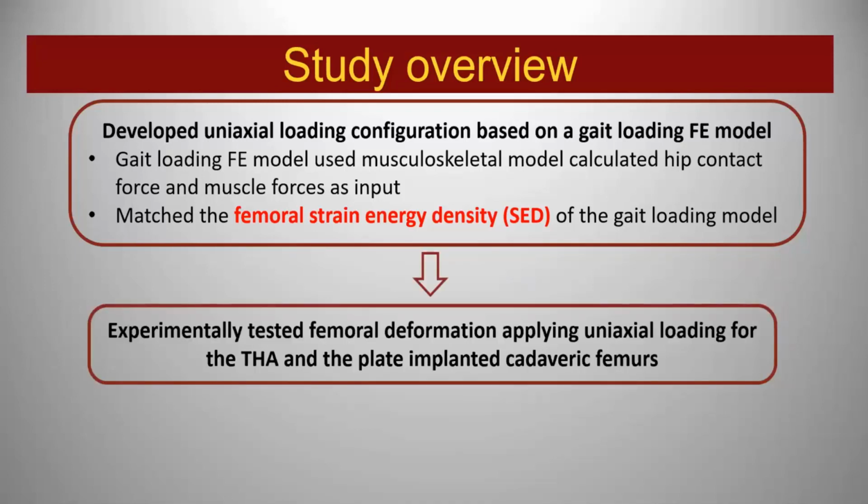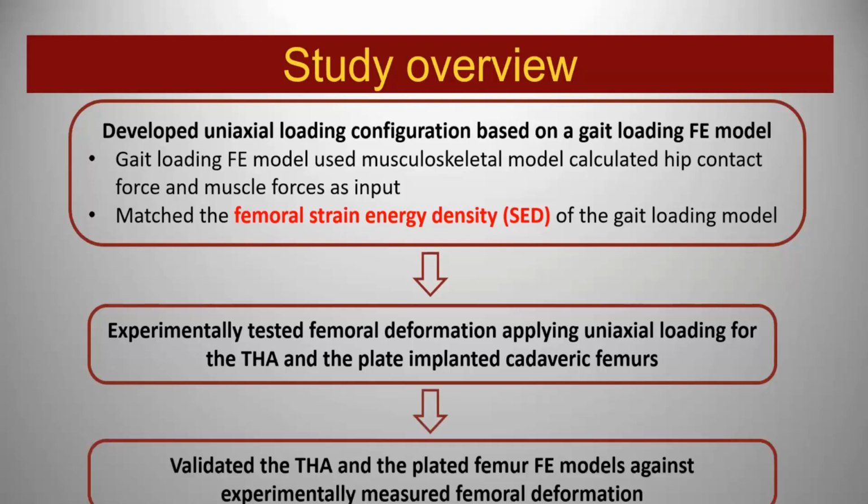And then we performed experimental validation using the femoral deformation of the model predicted results versus the experimental measured results for both the THA and the plate implanted cadaveric femurs. And using the validated THA and plated femoral models against experimental measured femoral deformation, we further calculated some strain outputs using the FE models.